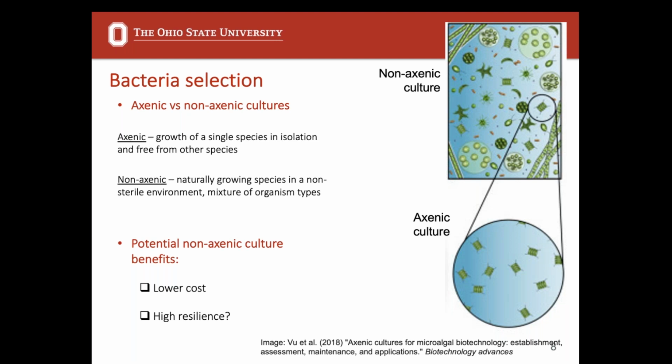So our thought was, why would we want to just use this single system that in nature is set up to fail when we could get a non-axenic culture from our local environment here in Ohio for pretty much free, and then propagate that bacteria and have a more resilient system that maybe can last longer, maybe secretes more carbonate material, and overall works better and is cheaper for us. And indeed, that study that I mentioned from Ghent actually showed a reduction in cost from taking this method of about an order of magnitude. So they reduced their cost by 10 times through use of an impure culture rather than the pure Bacillus subtilis culture. So we wanted to investigate doing that here in Ohio with the thought that we could lower our costs, increase the resilience of the system, and by taking samples in Ohio, maybe align the bacterial source with what it needs to survive in our specific Ohio environment, where we know it gets cold and not always the best weather.